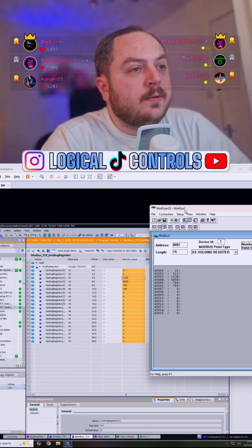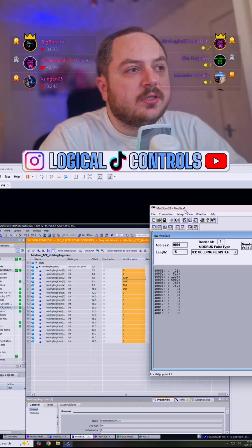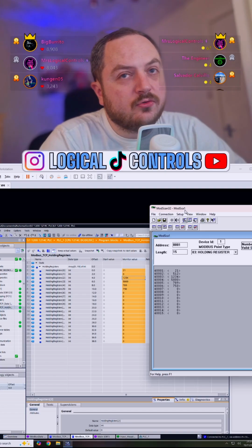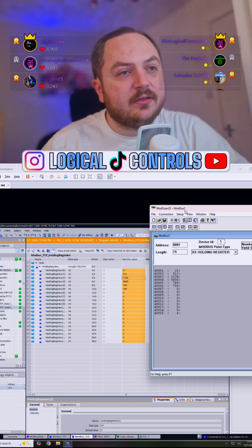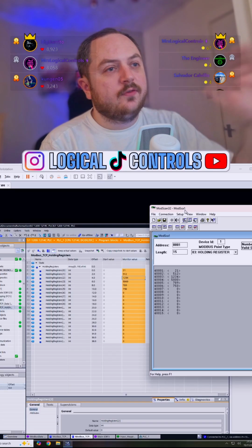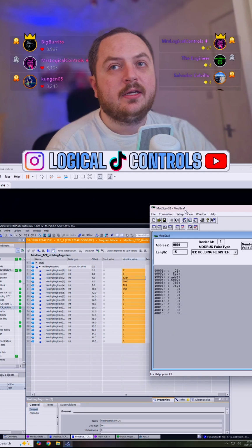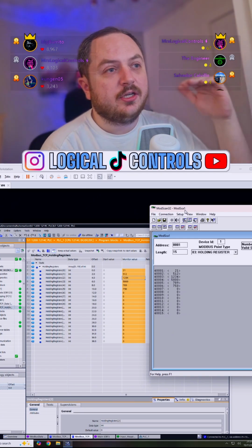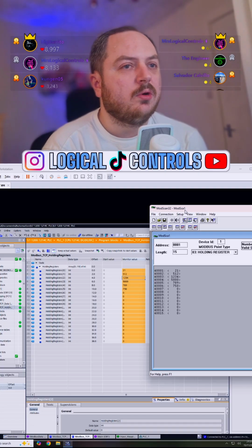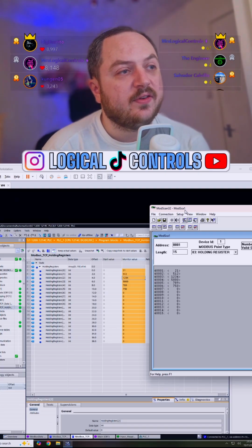Hope not. What is the best baud rate? So the baud rate is kind of dependent on the system, Snarky Man. If you go for a low baud rate, so 9600, you can actually read from devices much further away. The slower it is, the further you can go with your serial line. The higher it is, so the faster you're reading it, you have to make the line much shorter. But also, slower is much less likely to be subject to interference.